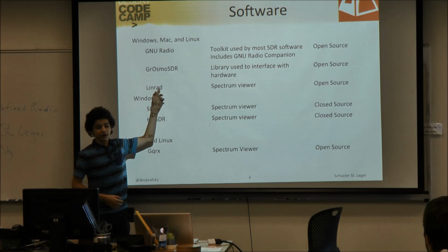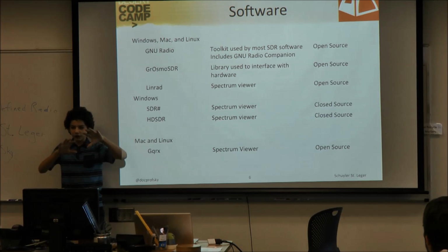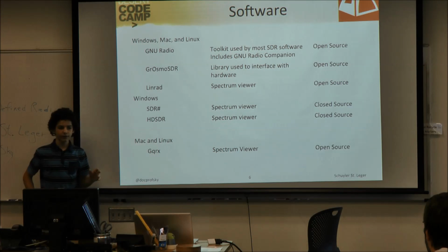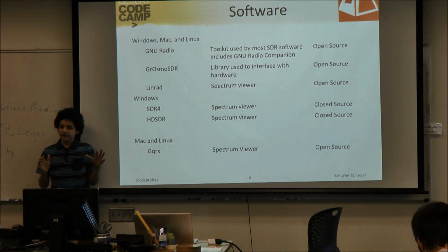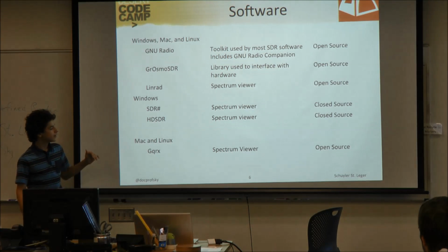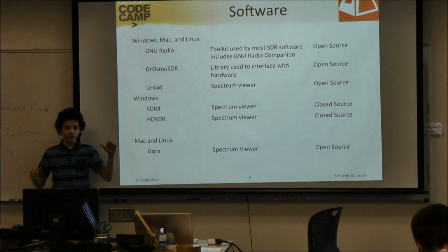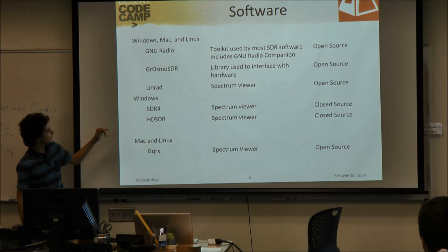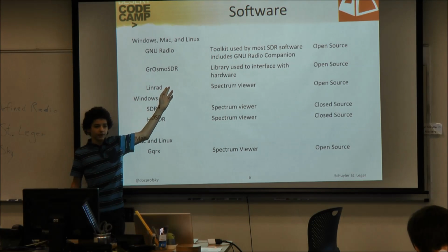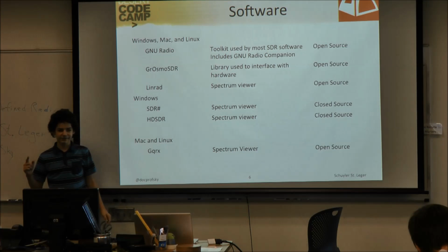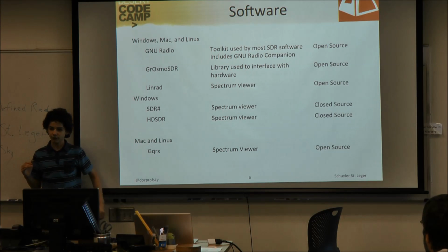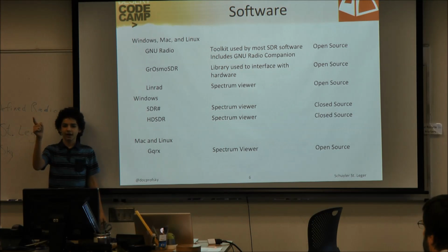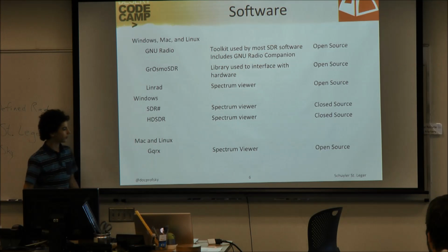There's gr-osmosdr. Now this is like all-in-one drivers for most of the hardware that I mentioned. So typically the way you'll see the software set up is you'll need to get the library for your specific device, but there's also the gr-osmosdr library that provides you with one block instead of 20 different ones for each different device you want to use. And this one block, you just tell it, I want to use BladeRF or HackRF or RTL-SDR or FunCube dongle.